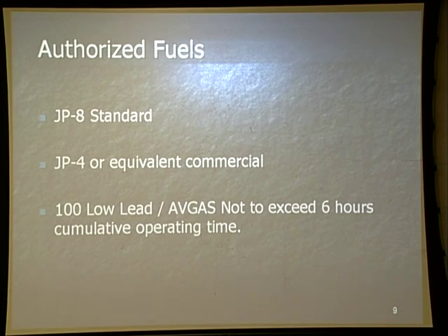Jet A, is that the same thing as low lead? Jet A is actually equivalent to JP4. Because back in the question it says JP4, JP5, JP8, and Jet A, and it doesn't talk about low lead. Well, this is an emergency fuel, not a regular fuel. The only time we plan on using this is in emergency situations. Meaning that's the only thing that's available and we need gas.